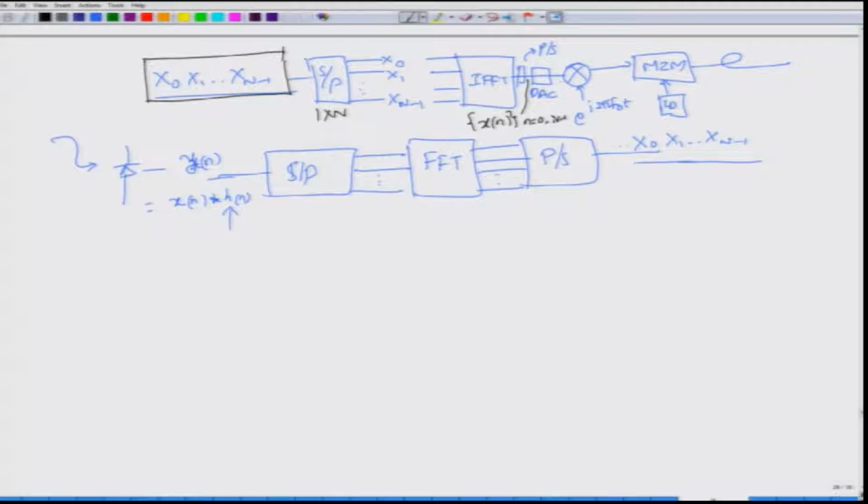These are converted into a digital waveform using a DAC. Usually you will have a real part as well as an imaginary part, and in this type of OFDM system, called a direct OFDM system, you first modulate this onto an RF carrier. So, what you generate here would be the RF OFDM. This RF OFDM signal is further modulated on the intensity of the optical carrier and launched into the fiber. At the receiver side, you put a photodetector to convert the optical signals into electrical signals.